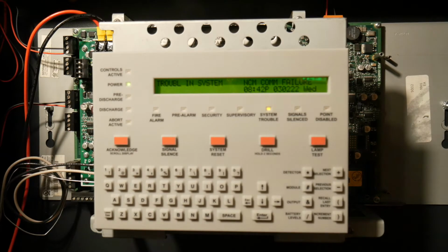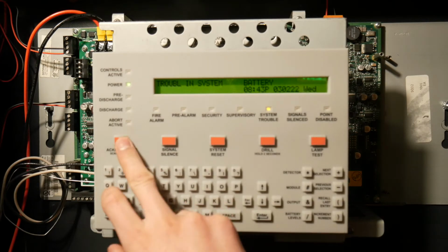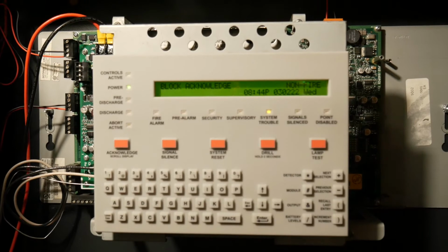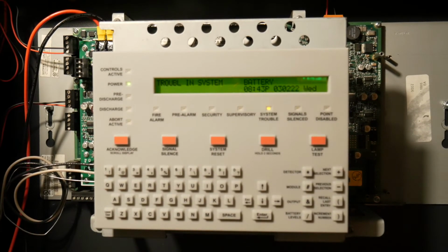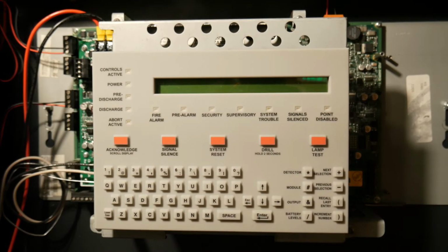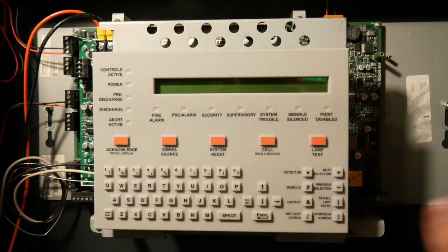So we're going to disconnect the batteries. A trouble should come up soon. We set this as a node, so it might take a while because the CPS 24 takes a while to talk to the main panel, but we got trouble. And I'm going to disconnect our power, and then we'll be good to go to disconnect the main display. Okay, we disconnected the power. Now we can unscrew the display and remove the ribbon cable, and we'll go from there.